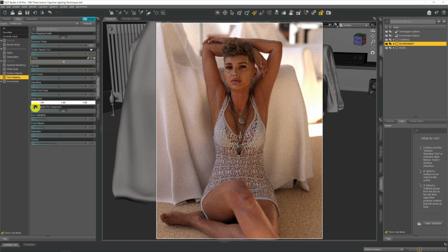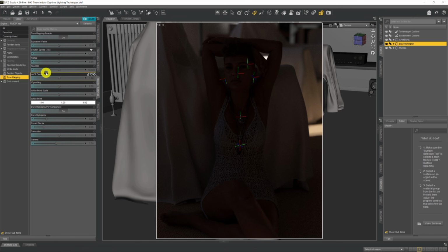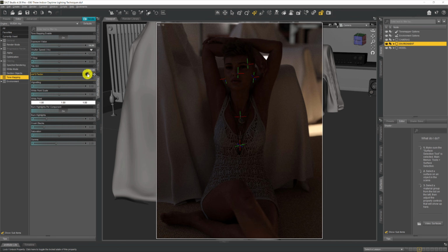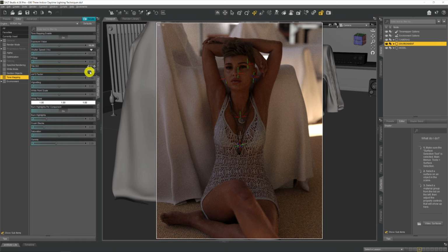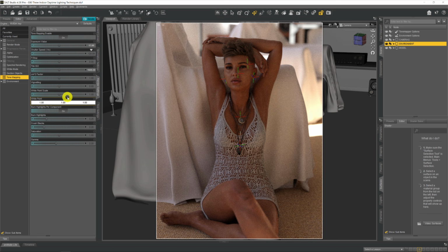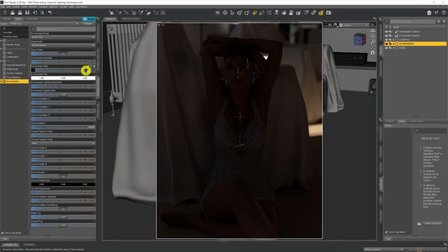If we put f-stop back to 8, back to its base, we can play around with film ISO, whichever you're comfortable with. They all do the same thing, but this time the bigger the number, the brighter the image will be. So it's at 100 at the moment. We'll go up to 200, brightens things up. We'll go up to 400, brightens things up more, up to 800. You know, and just play around with these things until you get the clarity of image that you want. It'll all be dependent on your scene and your initial lighting levels that you have in the first place. But yeah, that's doing it with a HDRI, the simplest, easiest method.